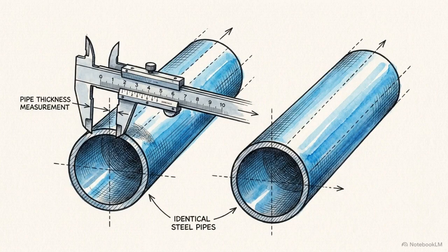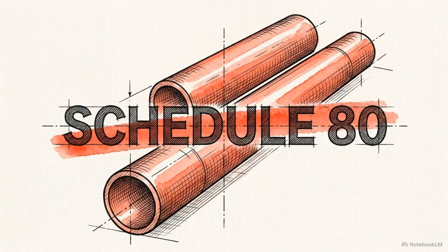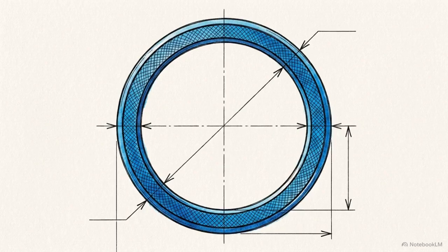Straight pipe follows its own logic. There is a common assumption that Schedule 80 is a synonym for high-pressure service, but the designation carries no direct pressure data. As established, a schedule number gives you zero published pressure data. It strictly dictates physical geometry.